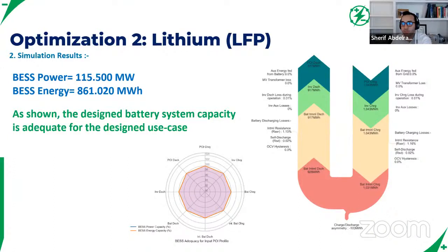That really keeps the focus on the battery technology itself. As you can see here with lithium, you're getting much higher than that 92% we're used to with lithium without the HVAC load. That's mainly because it's a high cycling application. You're not spending any time just sitting there.